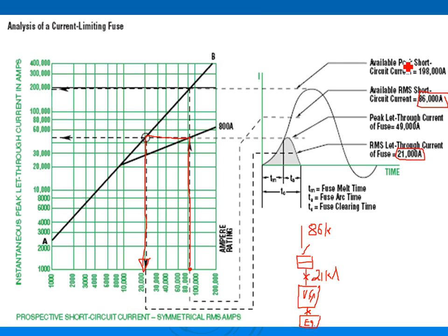The magnetic force, guys, is responsible for the peak. So if you continue up here, here's how much peak you could end up with right in here, but the fuse will knock it down, because it also knocks the peak of the signal down to this value. Here's the peak supposed to be this, and now it's going to knock it down to this value. Who cares? Now the shaking of your equipment is going to be almost 1/4 of what it should be. So you reduce the shaking and the baking of your equipment by installing current limiting fuses. Any comments, guys? Any questions?